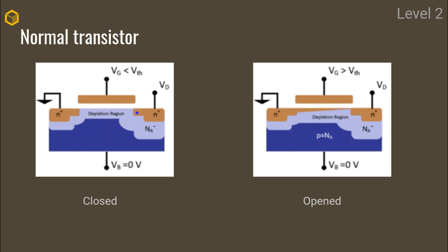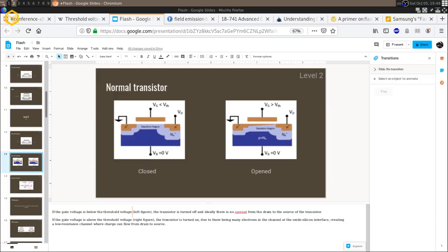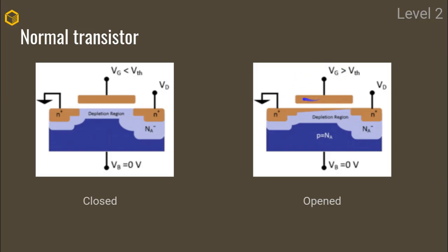And what you're actually going to create when you turn on the transistor is a bridge by applying, how can I put this very simply? By applying a certain amount of voltage that goes above the voltage threshold, I am actually going to create a bridge where, thanks to a field effect, my electrons are able to go from my source to my drain. And so my current is going to be able to flow. And so my switch is closed. And here my switch is open.